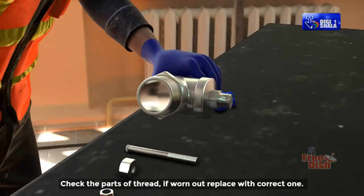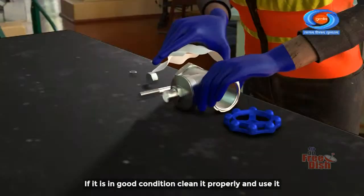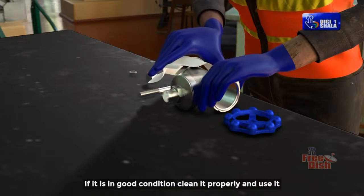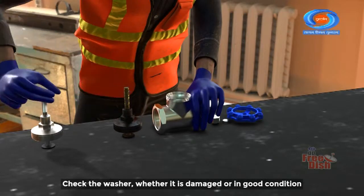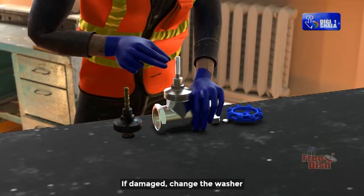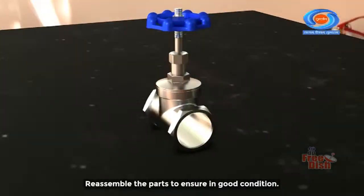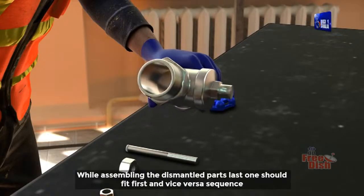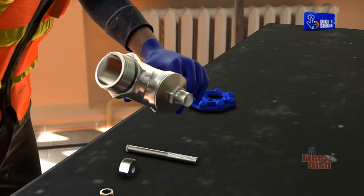Check the parts of thread. If worn out, replace with correct one. If it is in good condition, clean it properly and use it. Check the washer, whether it is damaged or in good condition. If damaged, change the washer. Reassemble the parts to ensure in good condition. While assembling the dismantled parts, last one should fit first and vice versa sequence.